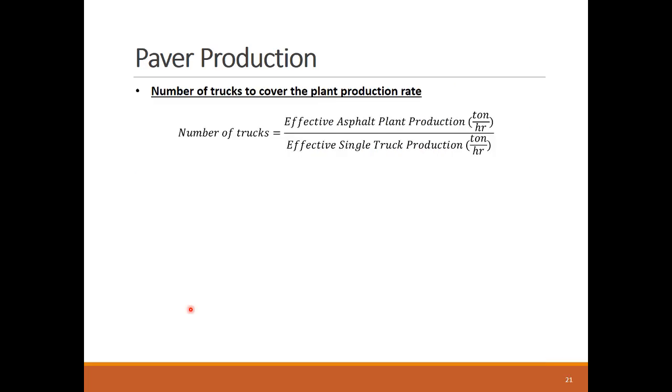We will use this simple formula to calculate the number of trucks needed to deliver the asphalt at the same rate it is produced. The truck production is here assumed to depend largely on its transit time, not much on the time of dumping the load in the paver.